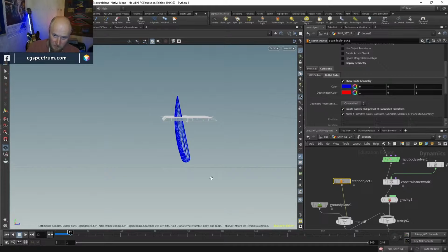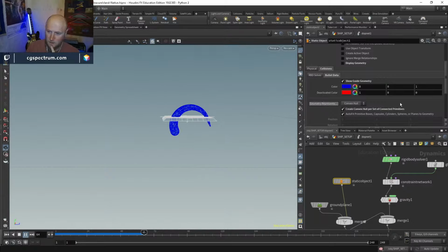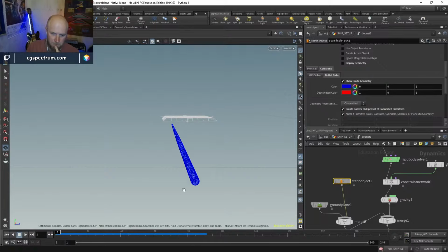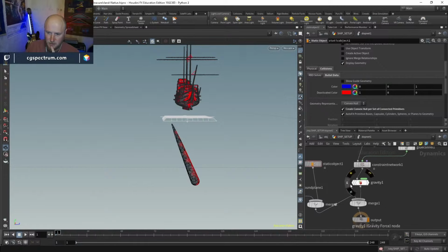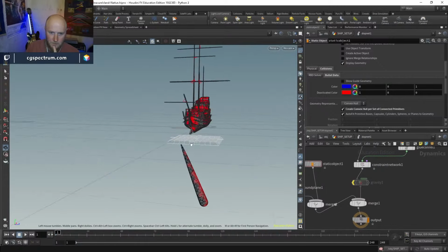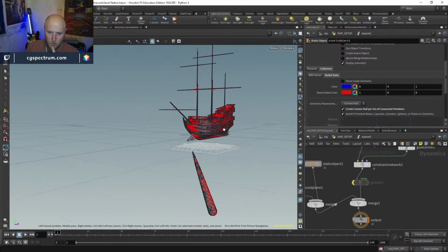Go back to frame 1. Changes to collision objects don't happen if you do it after the first frame. So make sure you're always on the first frame, or check, go back to the first frame. And now you can see, perfect collision. No stringing, or no stretching, and we're still using convex hull. So that's good. Turn that off. It's nice and fast. Let's turn gravity off again. And I'm doing that just so it doesn't fall before this collision happens.